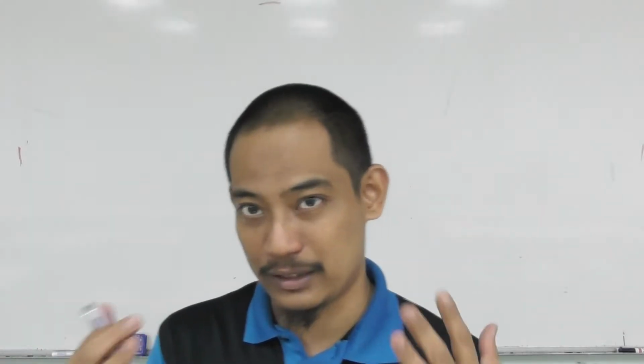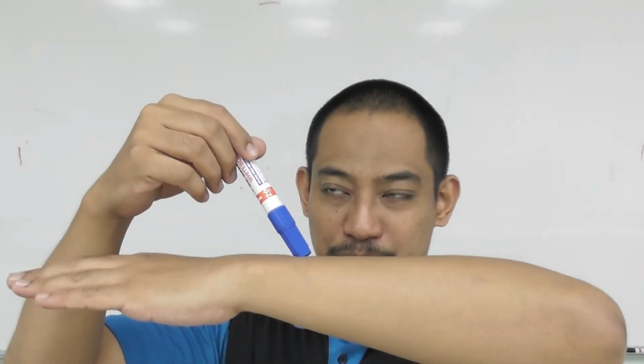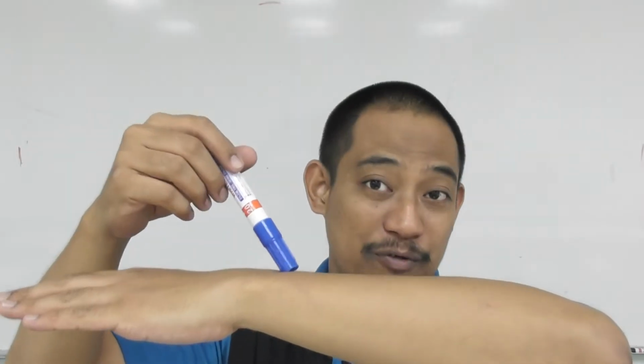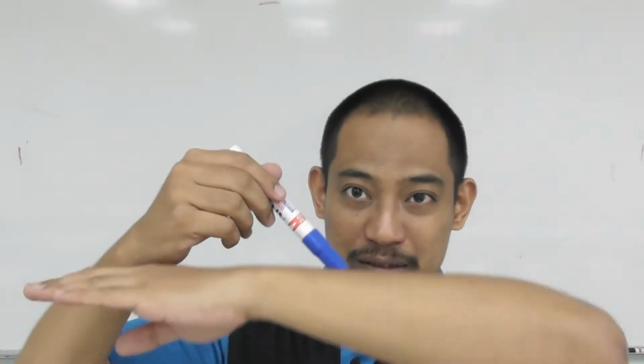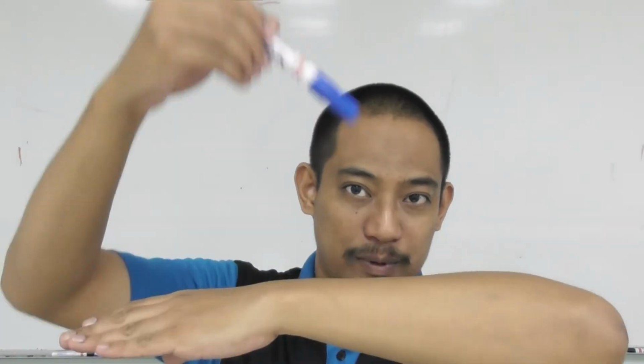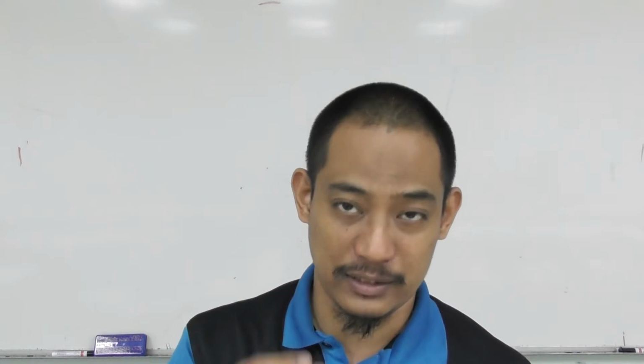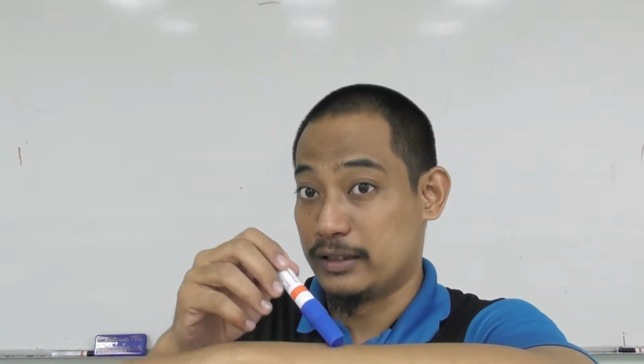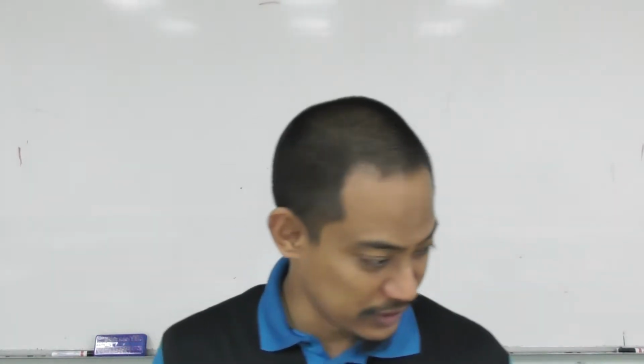So to reiterate, the question is, does this support prevent vertical movement, horizontal movement, and of course in 3D you have the three axes, right? This movement, and this movement, right? The only restriction is going down, right? And then does it restrict any rotation about this axis, and this axis, right? The three axes. So in this support, it doesn't restrict any rotation, right? And then you have ball and socket, right? Ball and socket is, what are the examples?